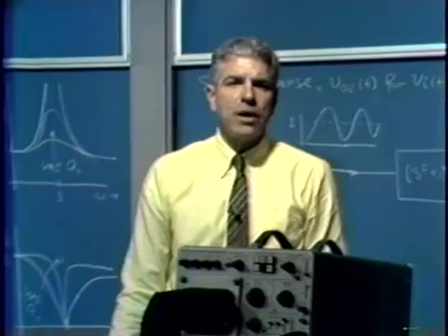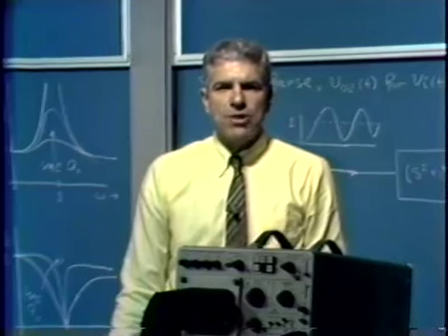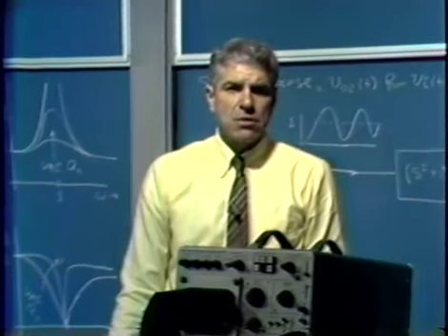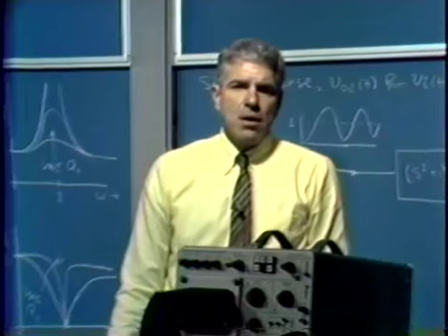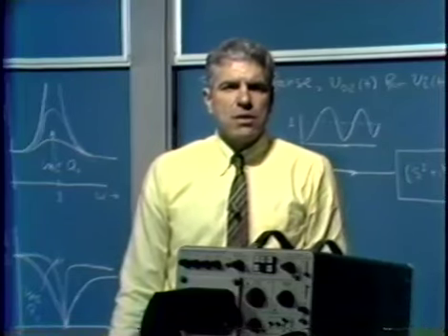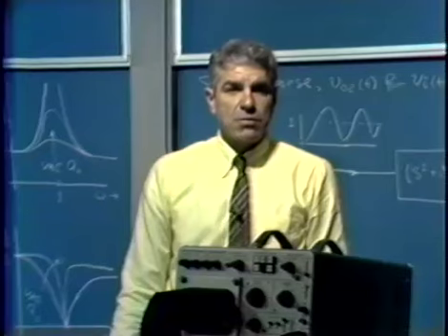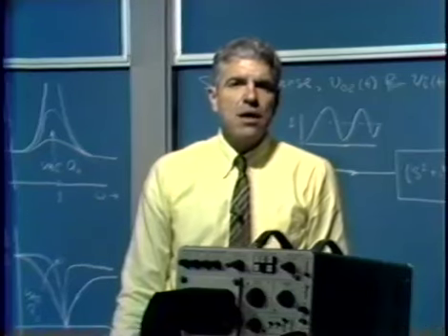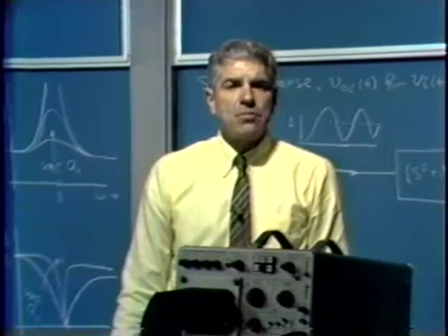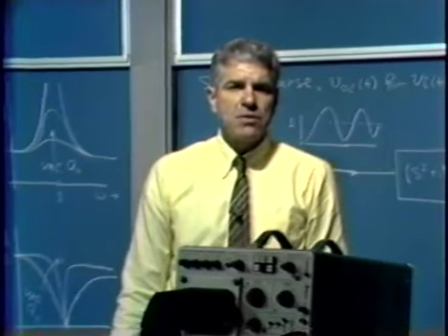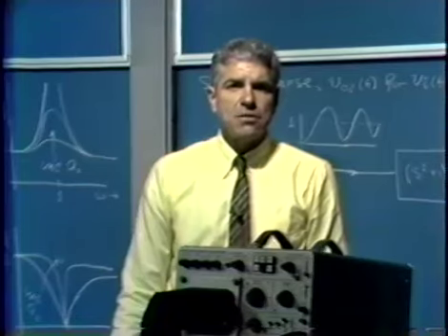So here's an example where, in order to get an overall appreciation for the system and the difficulties we may have with it, we have to look at the zeros as well as the poles that we get via our root locus analysis. We'll continue using root locus as an analytic and a design tool throughout the rest of the course, but this concludes our introduction to these techniques. Next time, we'll look at another method for analyzing the stability of feedback systems, and this one will be based on frequency response techniques. Thank you.